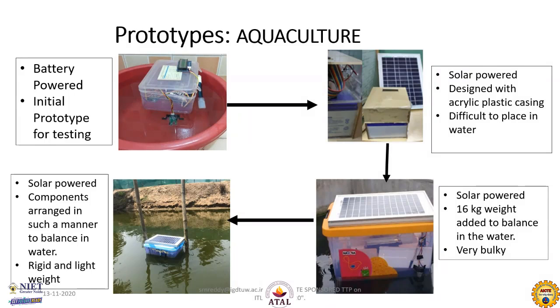When you keep the sensors in the water all the time, they get corroded, and due to scaling on the sensors, their sensitivity suffers. These are the two major issues we found, and we are trying to address them in further design.